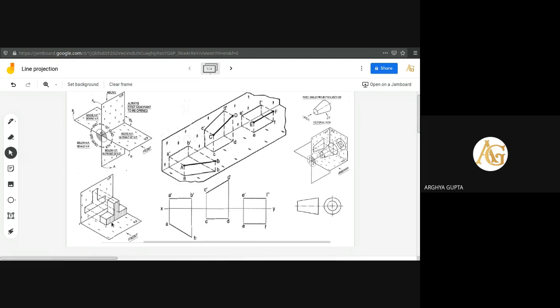Okay. So 2 mutually perpendicular views are possible, but in our drawing sheet, it is not possible to draw two mutually perpendicular planes, as it is a flat sheet. So we have to merge the horizontal plane with the vertical plane by rotating the horizontal plane clockwise 90 degrees. Then we get the front elevation or front view and the plan or top view.